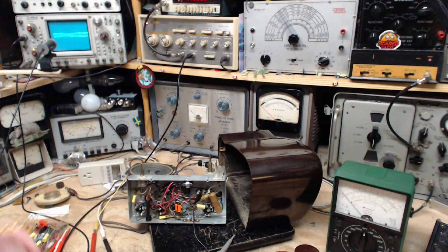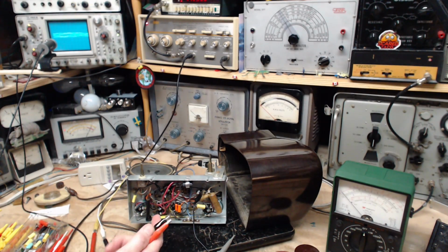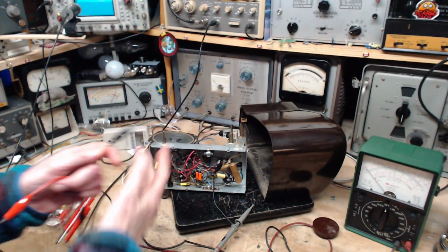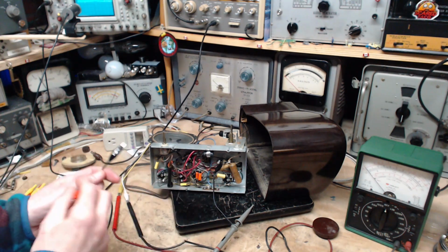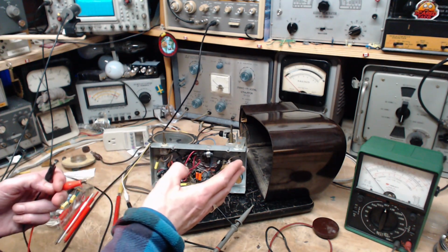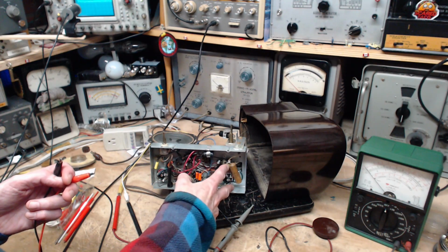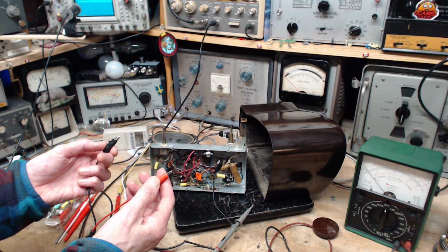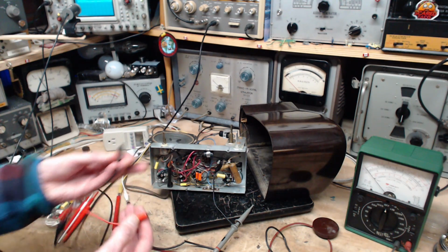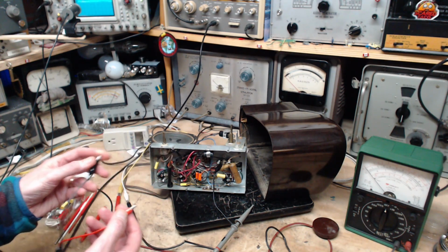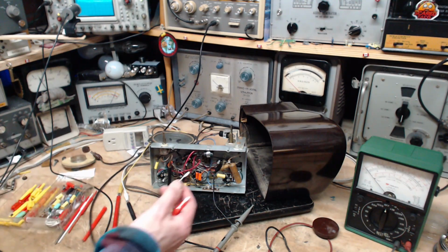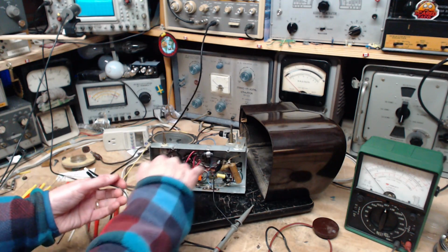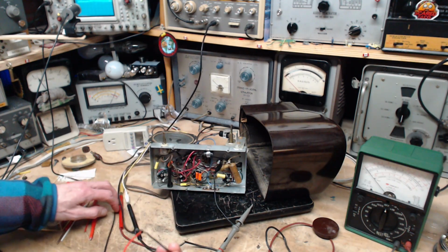So I've been thinking hard about this, how to make this connection. This is my signal generator here, and of course it's got the power system ground on it, and so does my oscilloscope, and I have this problem. I want the oscilloscope to be looking at the capacitor, so the connection should go to the chassis for that. I want this to feed a signal into the grid of a particular tube, and this should go to the B minus for that. And I can't do that. These two things are the same thing electrically. It would just be like putting a wire across from here to the grid.